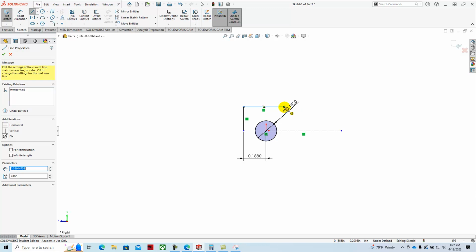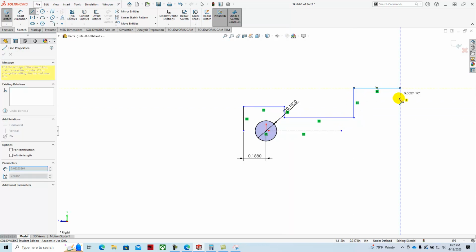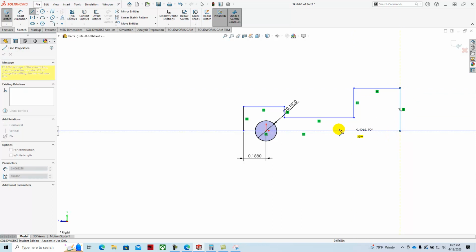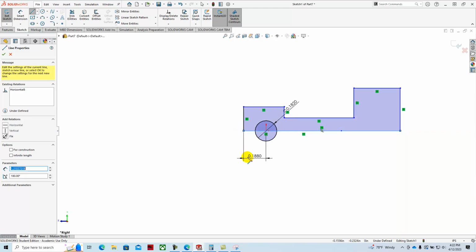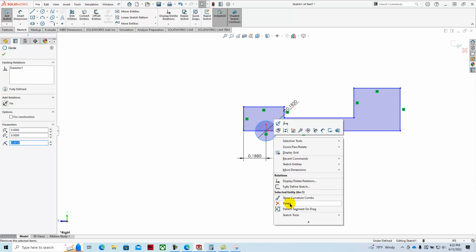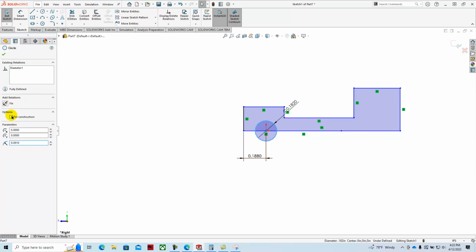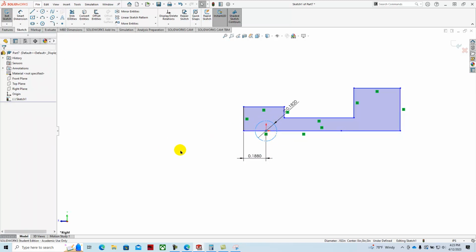And we can just continue with that to create this boundary shape. Hit escape. Like I said, we're going to delete this now that we have that geometry located there. Or rather than delete it, what we can do is select it and make it for construction. And that way it won't try to revolve it as we create this geometry.